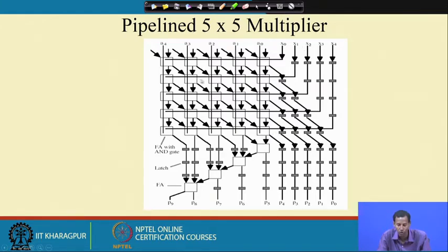The inputs are also passing after one delay element, so one processing element block delay. In total there are 5 processing element blocks, because at the final level I have to process through 4 blocks and one full adder cell delay for each block.